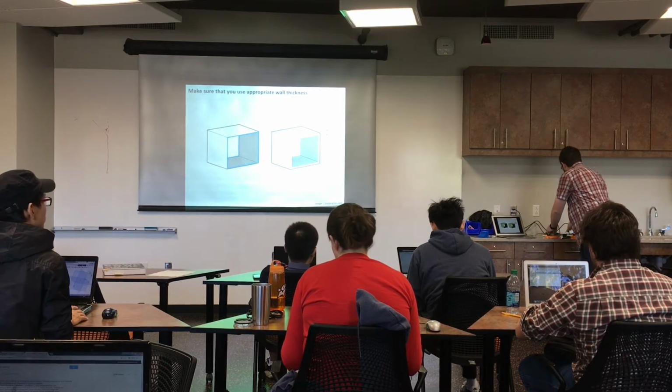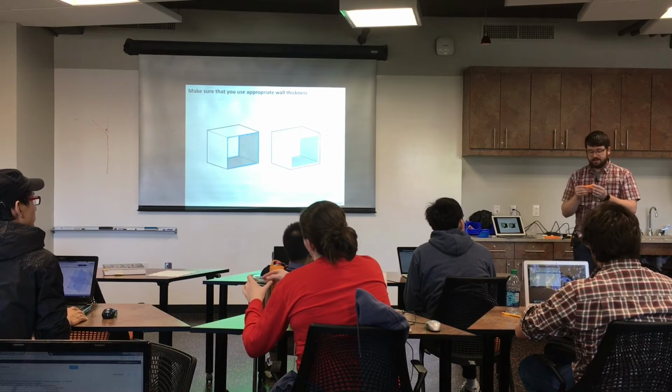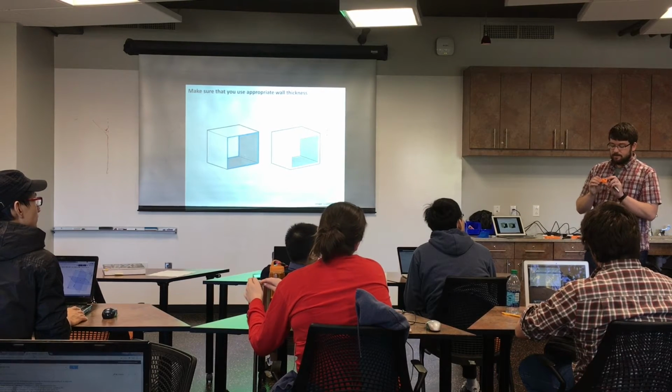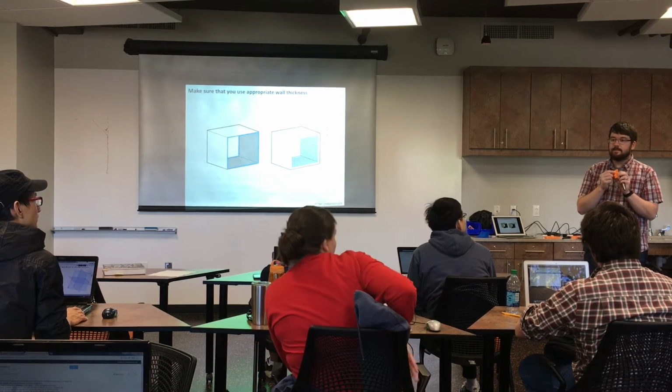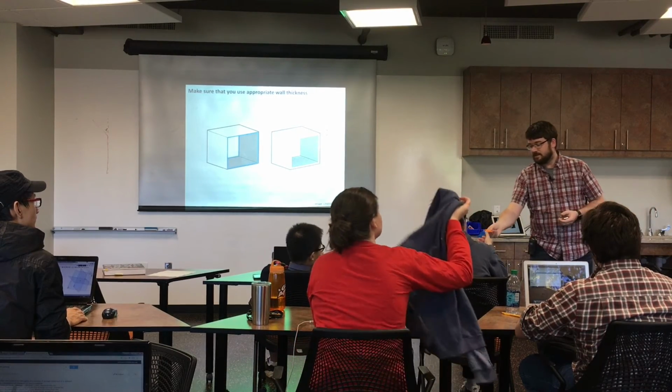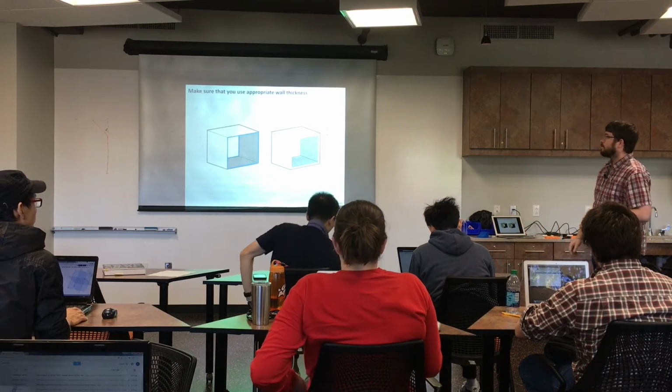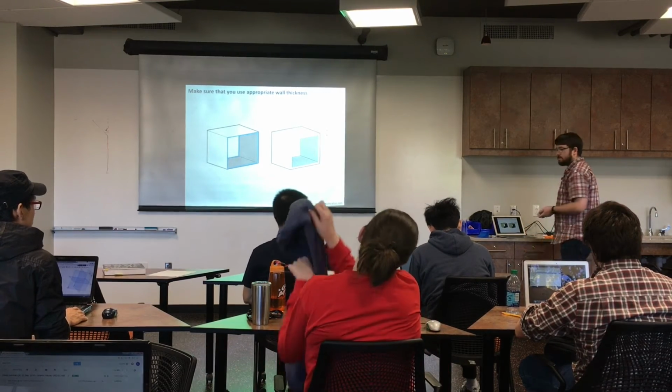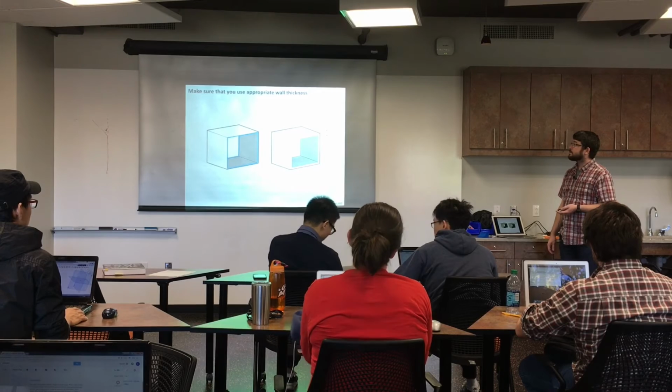I've got an example here, and I'll send these around. But you can see I tried really thin wall thicknesses up here, and you can actually see through the part in places. So you don't want to go quite that thin. And those had quite a few failed prints.